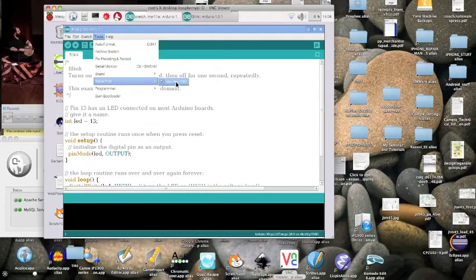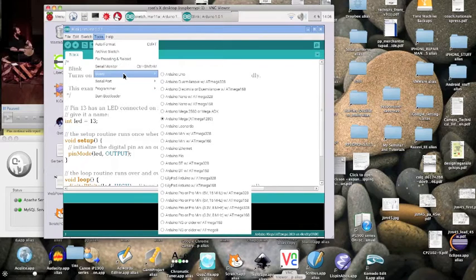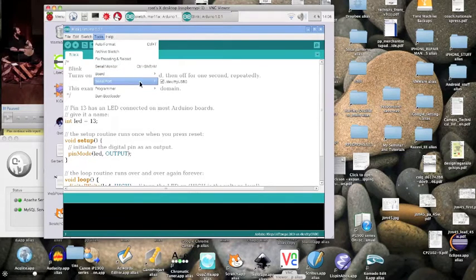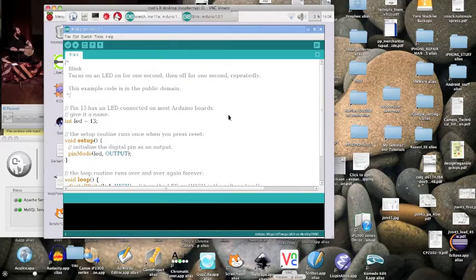And if you're still not sure, just try every one until it works. Basically, that's a lazy way of doing it. Open it up, and if you've got several in here, just try every one until the compile works. Then you know you've got the right serial port. So the important thing is to get the board correct and connect the right serial port. Once you've got those connected correctly, then you can compile it. Then it's all connected, and it should just go straight over to the board.